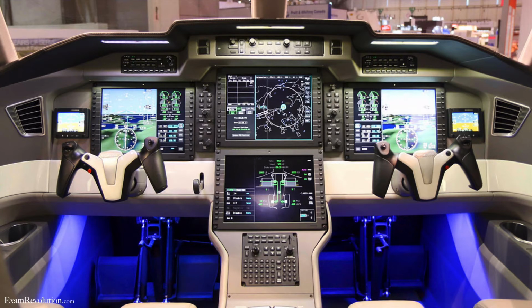And then on this side, you've got once again your PFD, and the information over here and over here is obviously basically the same. Depending on how you've set it up, you can change this side to show you not a HSI, but let's say a half HSI, or it can show you the terrain map, or whatever the case. You've got a few functions here on the side which you can change it to, and this is called the MCP, and I will show you guys this. It's called the mode control panel, right? And the mode control panel is basically the panel that you use to change the settings on the ADI, on the attitude director indicator. So you can take away the synthetic vision or whatever the case might be, and you can change the HSI into just half a HSI, or you can see terrain map there, or something like that. Depends on what functions obviously the system has, right?